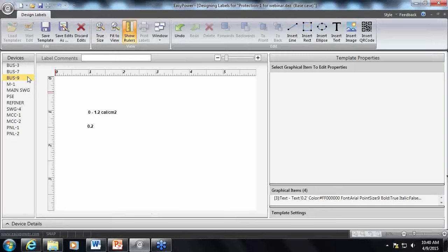This is one way that you could use basically the second condition in the equipment labeling in the NFPA 70, where you're looking at what is the minimum arc rating of the clothing. This might be one way to apply that, or the site-specific PPE levels. You could just call this your level. So that might be a way to solve a problem in the future, where the only labels you have to change would be the ones that were outside of this range, which require a different PPE.